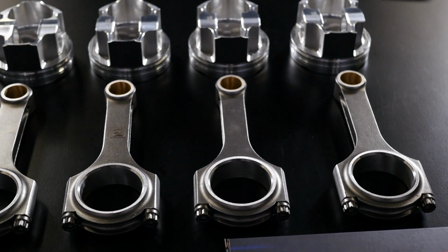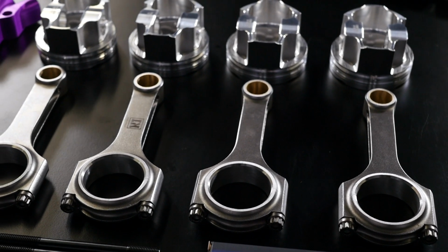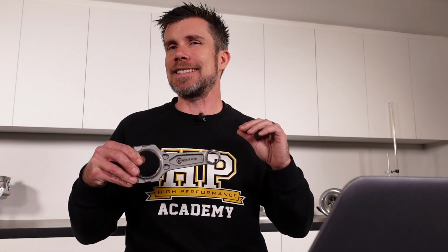There are two forces being applied to the connecting rod and they're very different, so we need to understand those. I've got a boost line connecting rod here just to give you a little bit of a visual idea of what's going on. The first force being applied to the connecting rod, which most people can understand, is a compressive force. That's trying to push the two ends of the rod together, and this increases as we increase cylinder pressure. It's the cylinder pressure acting down on the top of the piston being transferred down through the connecting rod. So that is a compressive force, and basically it's trying to bend or buckle the connecting rod in half. That doesn't really get affected by our RPM limit.